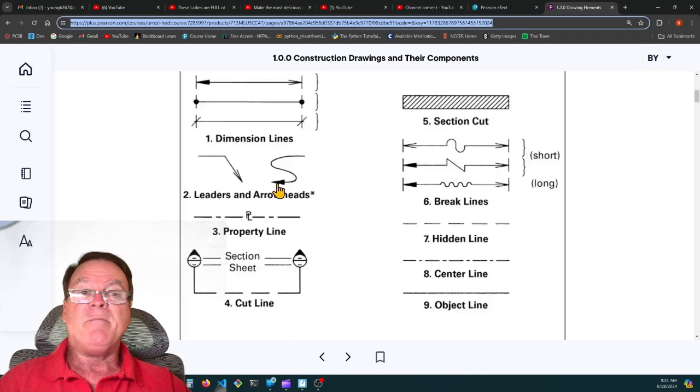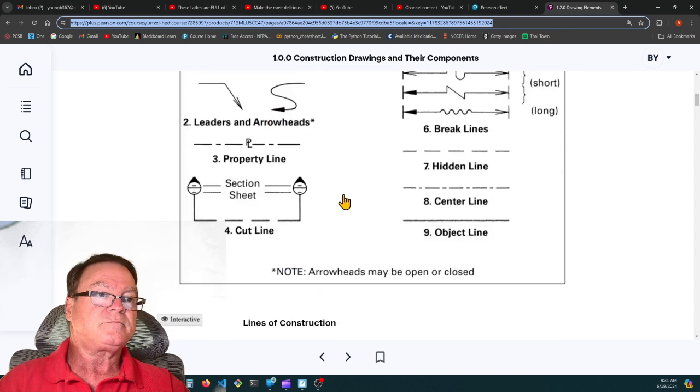Sometimes there may be an opening. There might be a circular opening, and it might say the diameter of that opening is 3 inches. And maybe on the drawing, it's too small to put any information inside that small little circle. So over here, it says 3-inch diameter, DIA, period. And it says that the opening, this hole, is 3 inches in diameter.